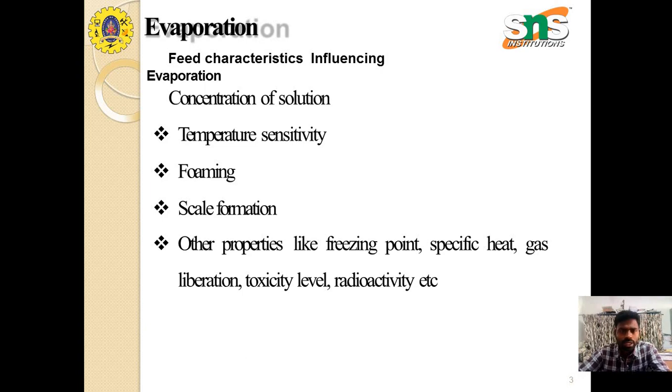And then temperature sensitivity. If the feed is more sensitive to temperature, it is easy to evaporate. If it is less sensitive, it takes more time to evaporate. And then foaming. Once the evaporation process starts, some solutions may form foam on the surface of the solution.